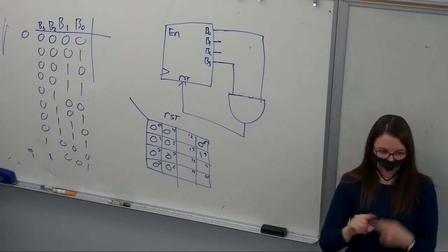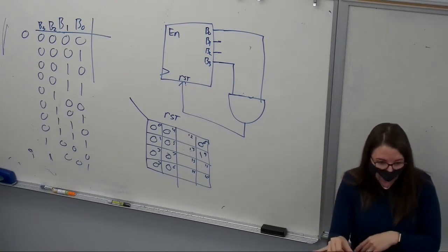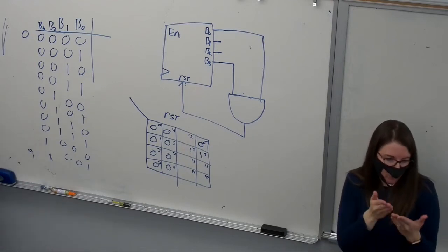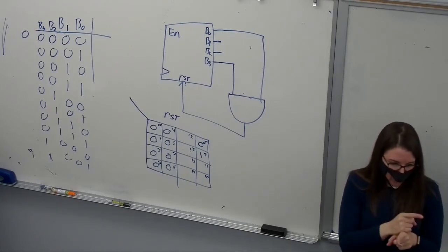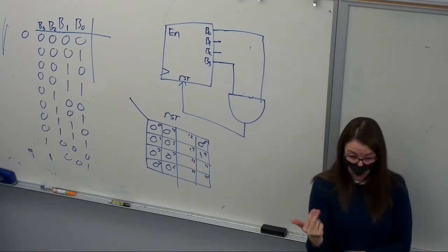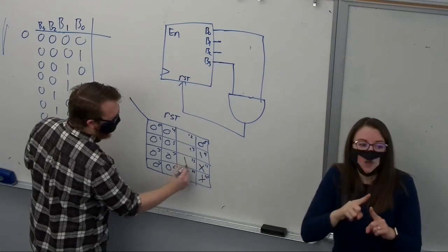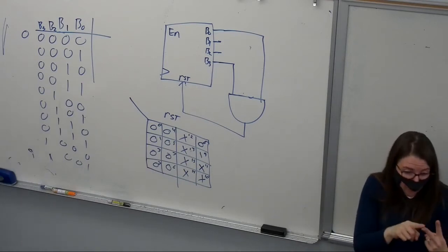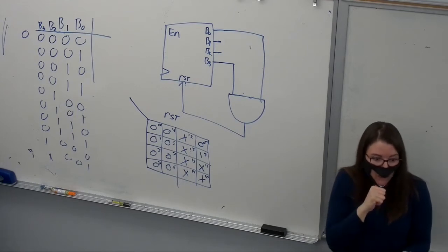That's what that says. Now, everything after that should never happen, right? So the two ways we could do it, the less correct way is write 1s at all of those, which would say, if you ever ended up in this state, reset because something weird happened. But really, we would like to say that we should never end up here. So we can just fill in the rest of that K-map with don't cares. I don't care because it should never happen, right? That's one of our conditions for don't care.